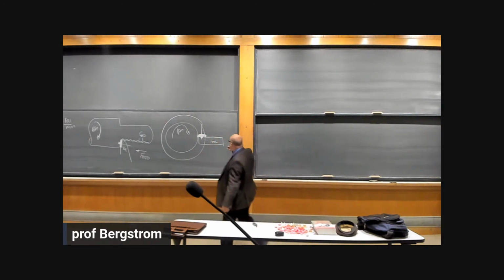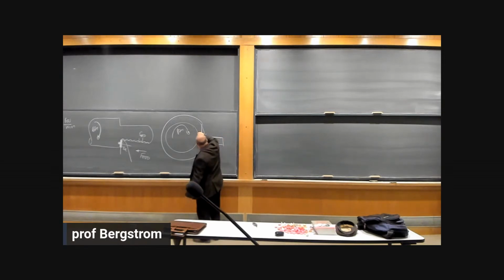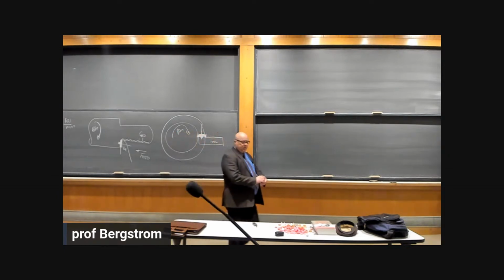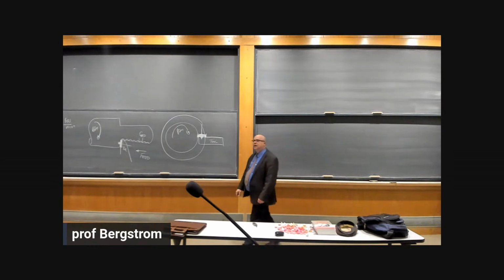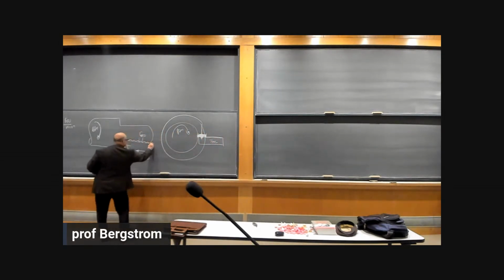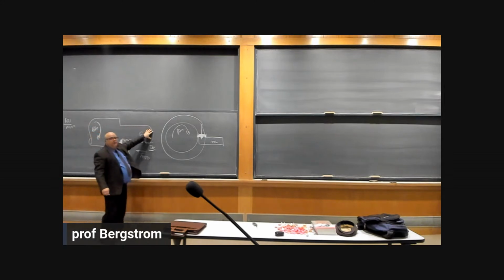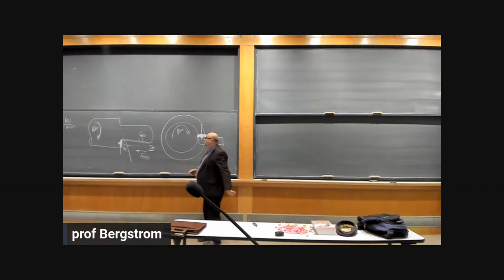And what's this distance here? That's the depth of cut. So that's equal to this distance here. And the initial diameter minus the final diameter is 2 times the depth of cut. So we've got all that geometry.